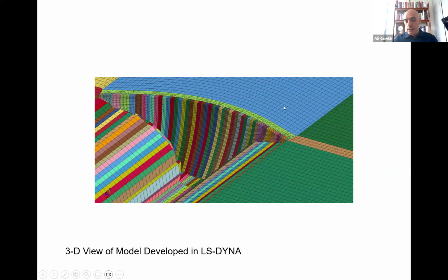On the water side, accidentally the water turned out to be blue. So this is mostly water. For the water close to the dam, we use different mesh techniques, and the program has just used a different color. The water is also continuous. So the only places where there is separation are between monoliths, where we use frictional contact, and at the base of monoliths, where we again use frictional contact, similar to what I explained in more detail in the Panama Canal case.